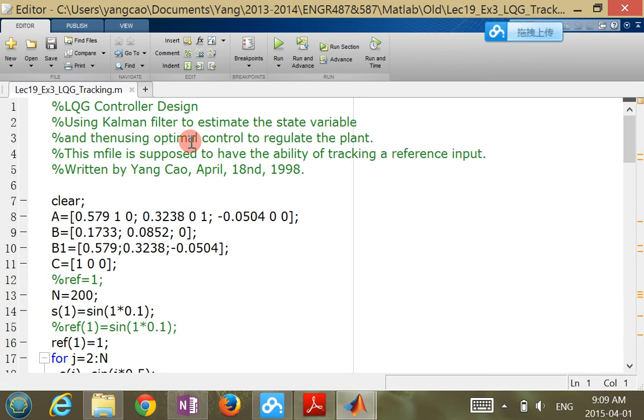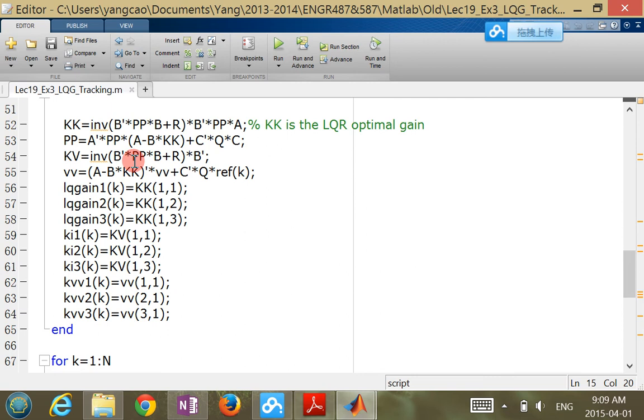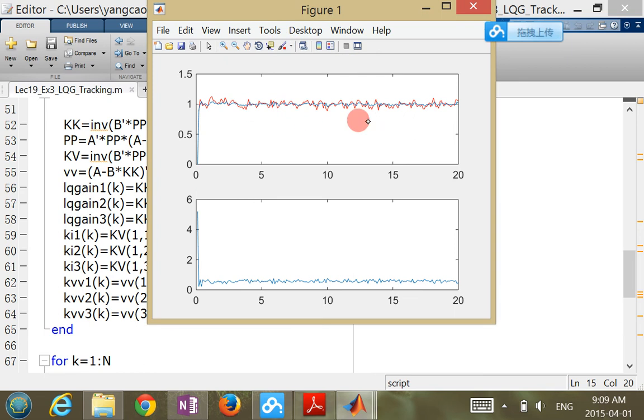If you want to implement this, you probably need to look at how you input it. There's some offline calculation you may need to get the steady state value of some of the parameters. So talk to me if you are interested. All right. If you run it, this is what happens here, because it's a noisy system. Do you remember which one is which now? Apparently, it goes to the steady state, the step output response here. One of them is the estimate, and the other one is the actual.